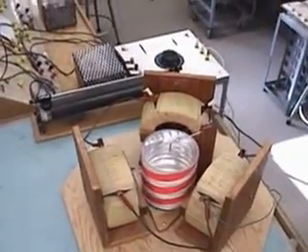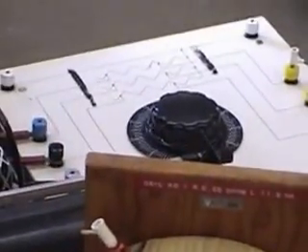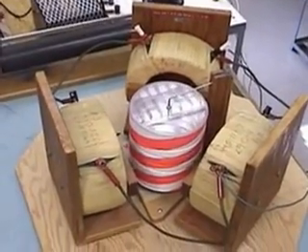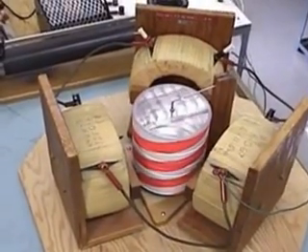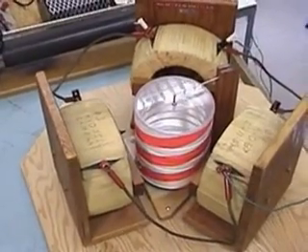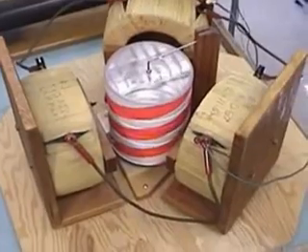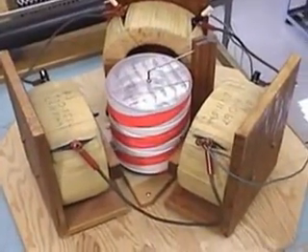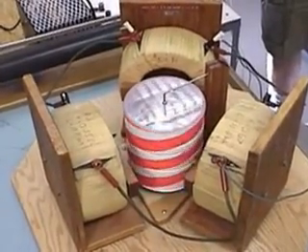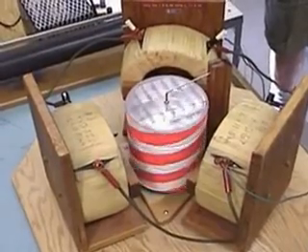In this experiment, instead of setting up a squirrel cage in the center of the machine, I put a coffee can. Yes, the coffee can works like a squirrel cage with an infinite number of vertical conductors. Three coils strategically located 120 degrees apart are fed by a set of three-phase currents fed from a busy hydro power outlet. A rotating magnetic field will appear in a moment, and that field will induce currents and will apply torques on the coffee can and make it turn about. Observe. It works just the way Tesla predicted it would.